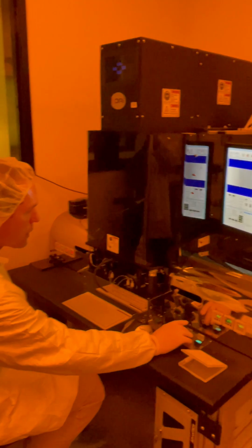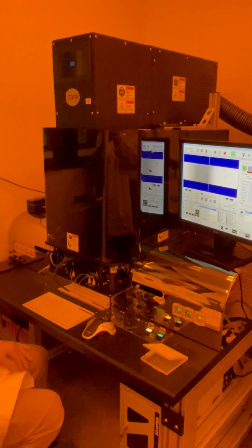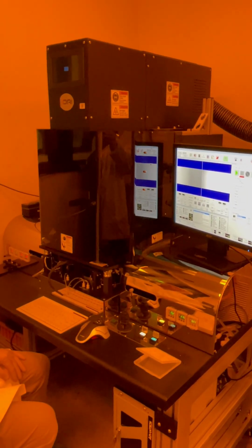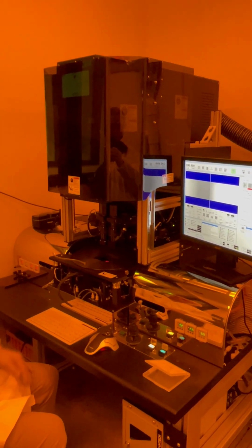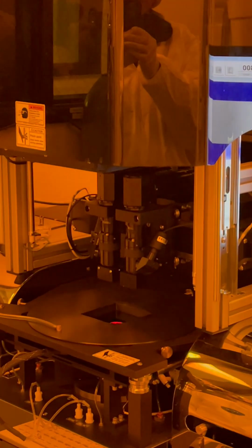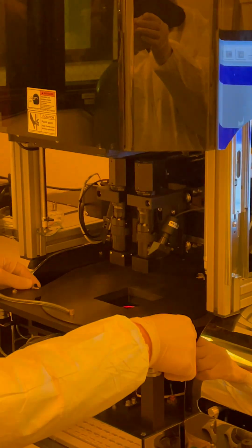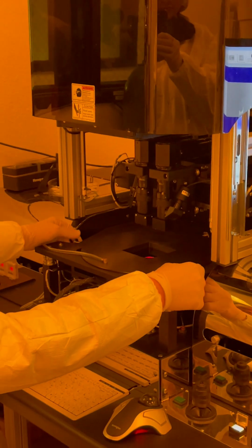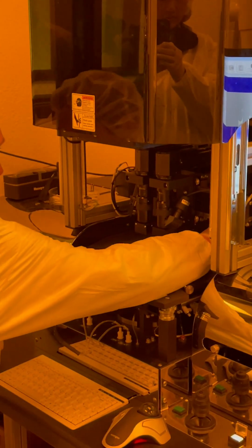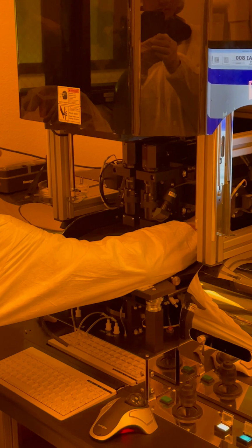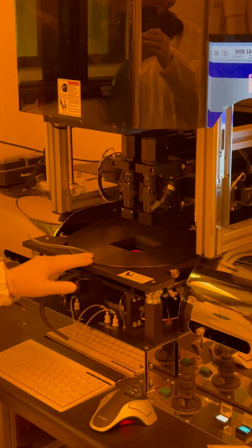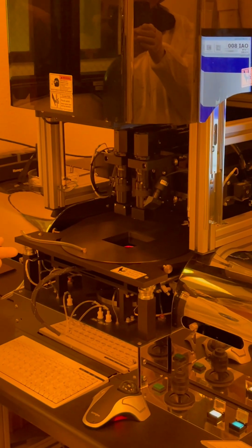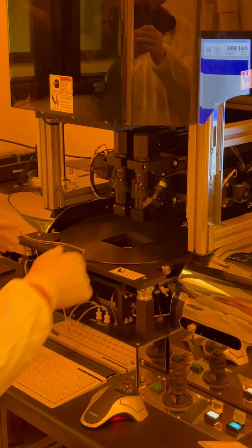Let's see. So we can just go through loading, getting set up first. You've got your process area here, microscopes. So if you're going to load a mask and a chuck, basically what you do, you have these 3 thumb screws here. And actually, I think on the new systems, these have been replaced by automatic air cylinders. So it's a little easier, but basically the same thing.